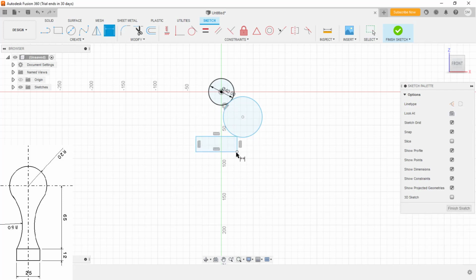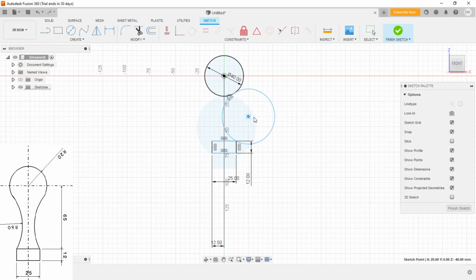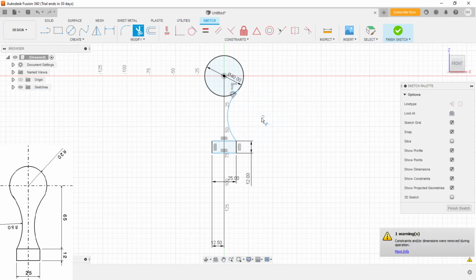I need the rectangle, so press the S key and select rectangle. This point on the circle is a reference. Dimension, this is given 25. From this to here I can take half of this, 12.5. 25 by 2 you can take it. This is 12.5. Yeah, this is done. We can drag it out like this and trim it better. T is the shortcut for trimming.